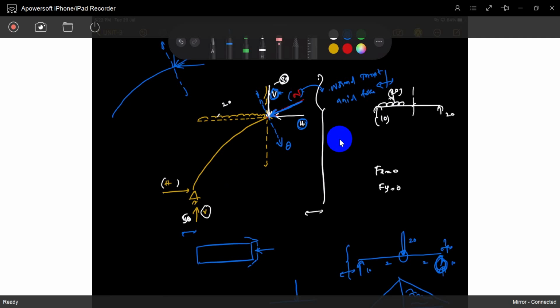The loads are distributed throughout the span by moments and also by axial force. That's why another one of the scientists says that the loads are distributed throughout the span not only by moments but also some axial force. That's why the moments are considerably reduced compared with the linear span. In a linear span, the loads are distributed through moments only. That's why some sections have some moments, but when the same loads are applied in the arches, the loads are distributed through moments and also some axial force. So some part goes inside in the form of axial force, then the moments are considerably reduced. It's just a feeling, not exact.